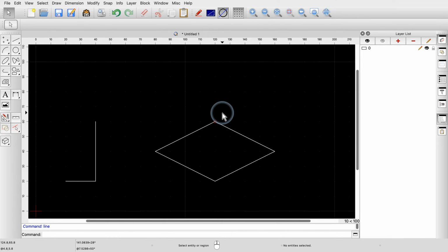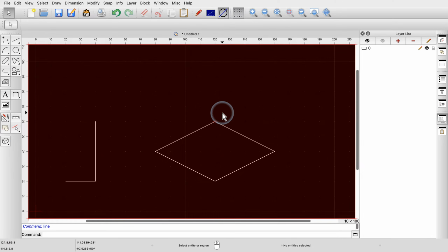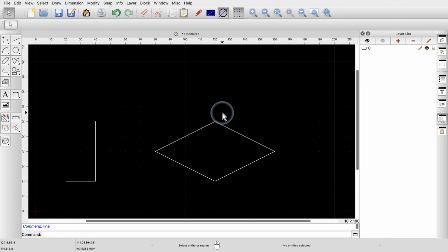This is how most of the construction tools in QCAD work. First, we choose the construction tool in the CAD toolbar. Then, we click reference points or entities in the drawing area. And when we are done, we click the right mouse button or use the escape key to stop the tool. After stopping a tool, QCAD is back in its neutral state, just like when it was started. This means that no construction tools are active at the moment. In this neutral state, we can view the drawing and do some basic modifications such as selecting and deleting entities.